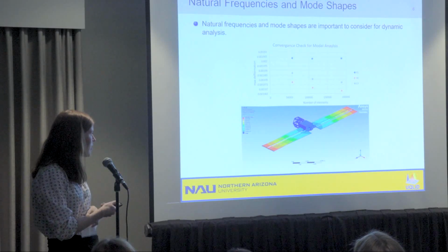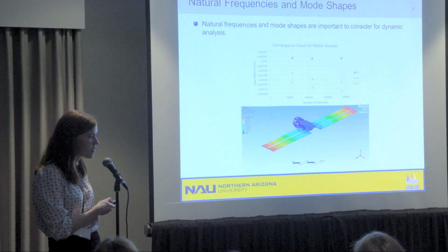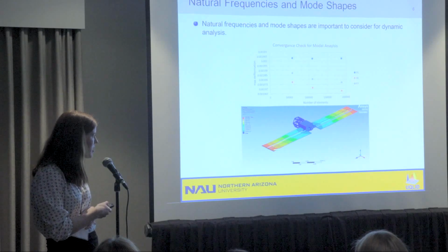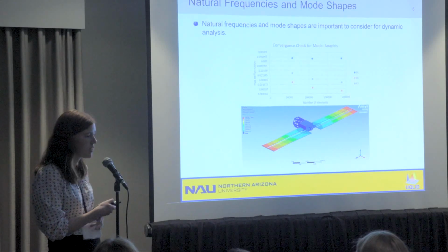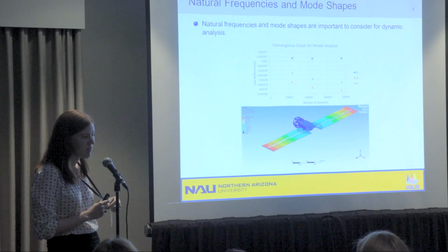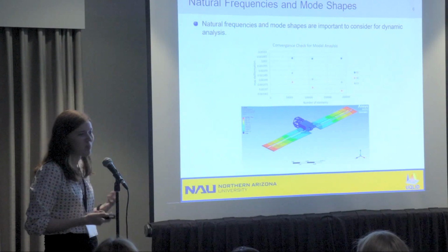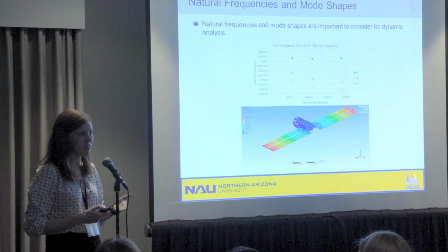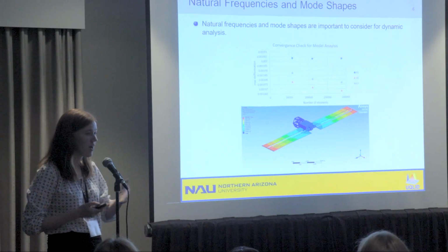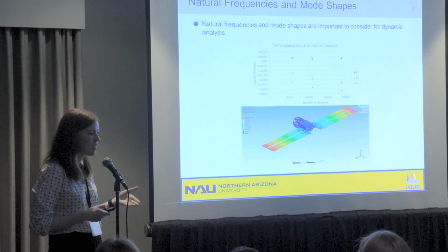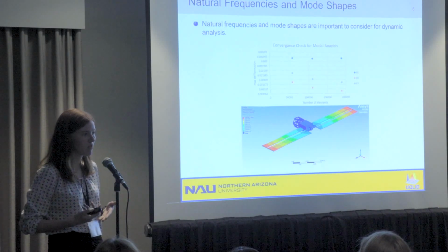And then this graph here is our first natural frequency. You can see the max deformation is on both sides for that frequency. This has a slightly higher max deformation of about 1 millimeter. So it makes a big difference when you have natural frequencies. It's roughly an order of magnitude higher for a natural frequency deformation versus just a static loading condition.